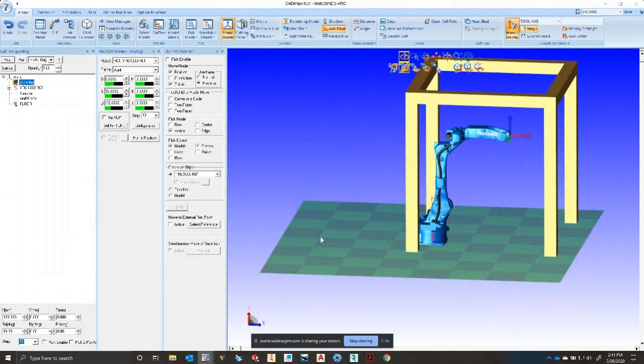If you open every single part in your assembly as its own part and then export, its origin may be in a different location than the assembly origin, and therefore it will not line up in MotoSim. You can definitely move the parts around in MotoSim, it's just that you have to guess. So if you want to replicate your cell, always work from the top level assembly. We do have videos on our YouTube channel that talk about this.